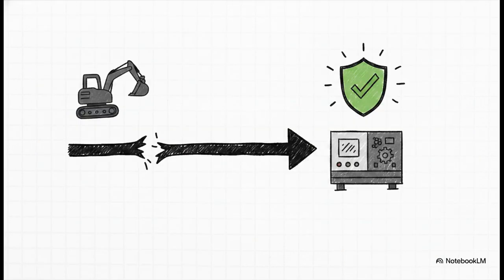And that brings us to the brilliant concept of the failsafe. If you use a B contact for an emergency stop, power is constantly flowing. But what if that same rat chews the wire? The current instantly drops to zero. And here's the genius part. The machine's system interprets that sudden lack of current exactly the same way as someone smashing the e-stop button. It triggers an automatic, safe shutdown immediately. Even if the equipment physically breaks, it fails in a safe way. Honestly, that kind of engineering is just so cool.